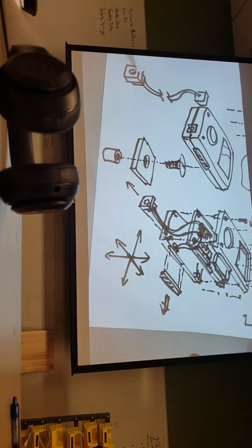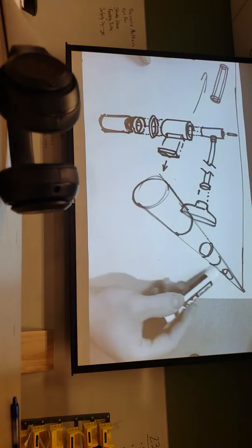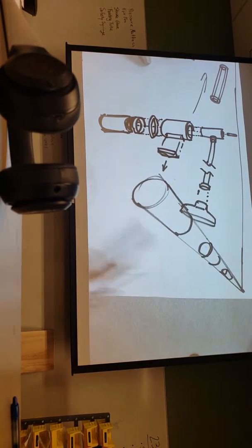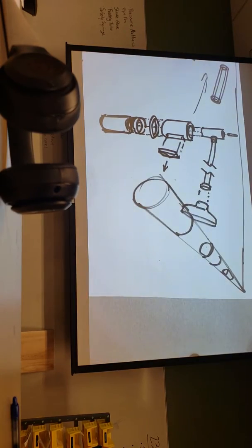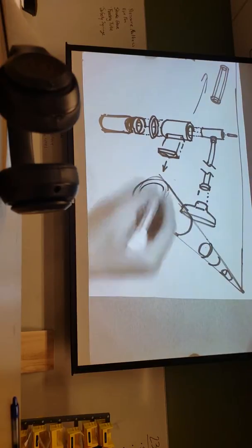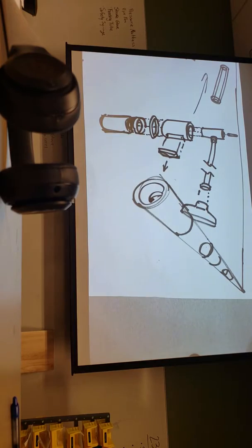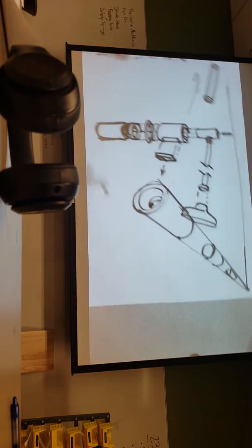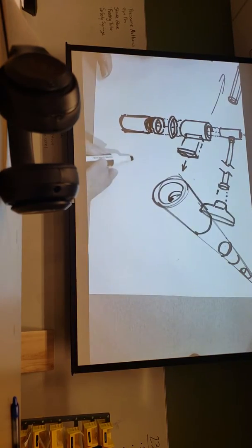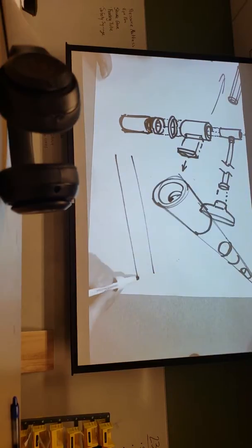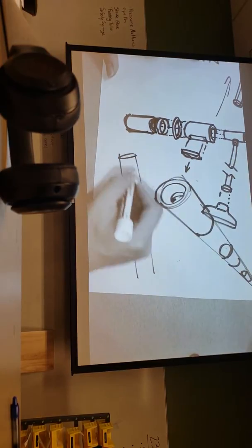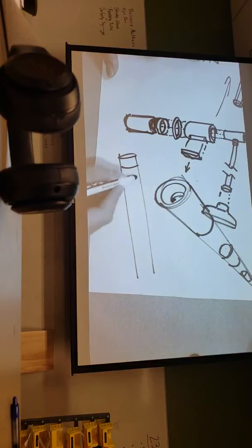Okay. All right. So that's somewhat of the basics of exploded views. By the way, if you do have a tubular object and you want to do it this way with a vanishing point, it's probably not a good idea, because you end up with a very big component in the front, but shrinking components at the back. So what I tell students to do if they like to do a horizontal layout is to use something that's more of an isometric method of drawing exploded objects.